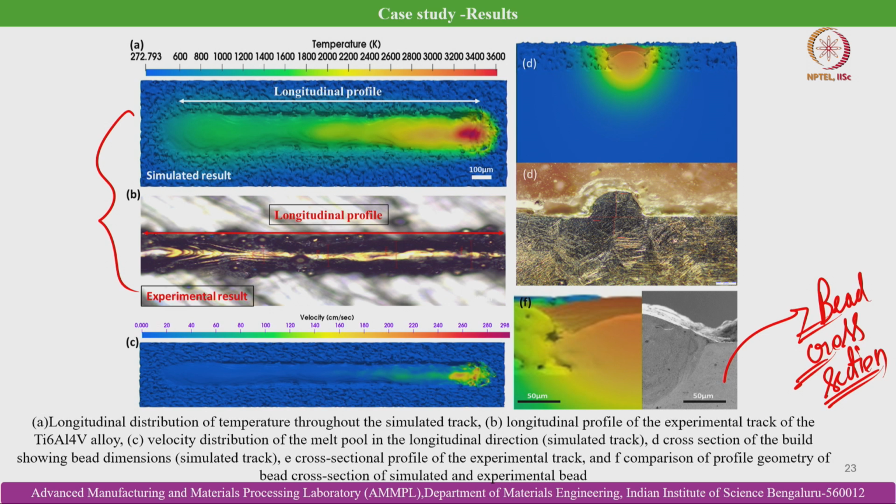And also thereby it helps to optimize the process variables in case of LPBF, like I discussed with you earlier: laser power, scan speed, spot radius, and also powder particle morphology. So, these are the important variables, and also the layer height, etc.